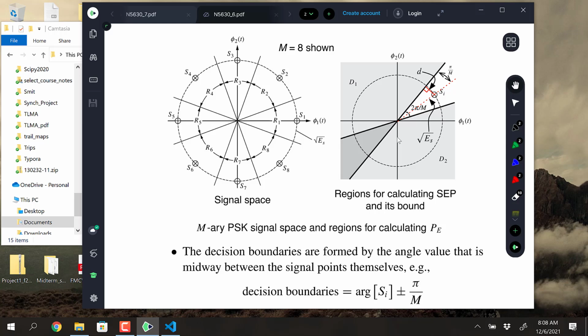So the energy per bit that you have to put into the system is the same, and you get the same error probability. What makes QPSK not as desirable as BPSK, though, is if there is a phase error, then there's a slight rotation, and you project. You get crosstalk, because some of the quadrature will project onto the real axis and vice versa. So you have more complexity. You have to maintain the phase balance, and of course amplitude balance goes along with that, but the phase imbalance would be where you're not perfectly in quadrature. So that is an impact, but other than that, the serial bit error probability is the same.